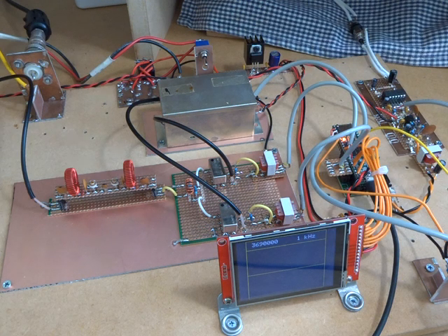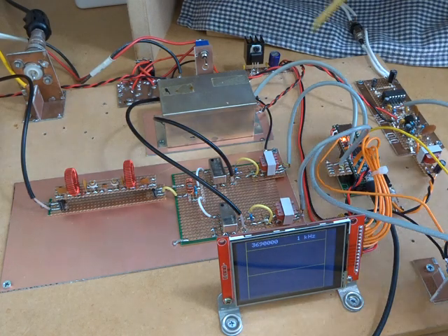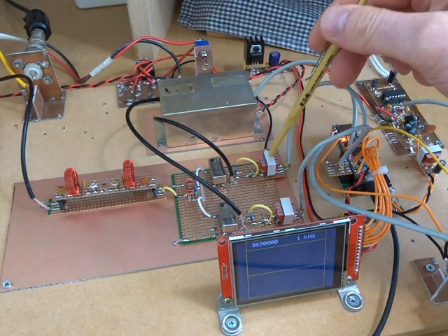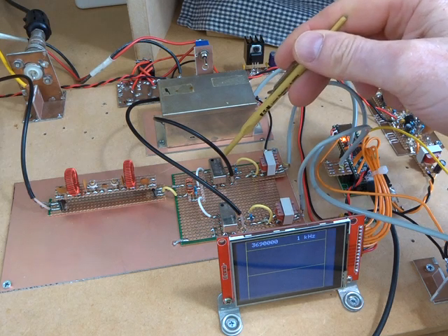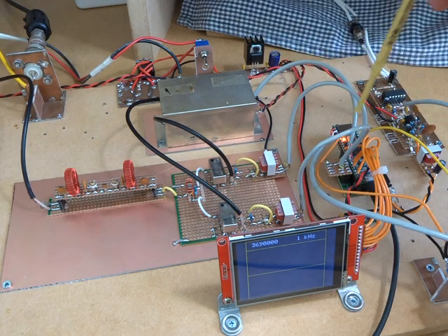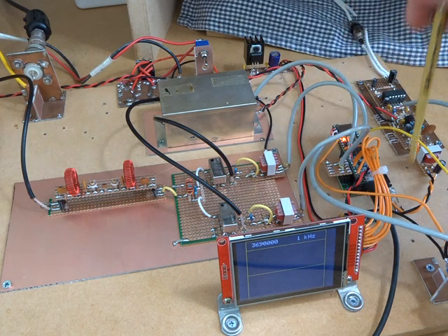So in terms of some changes since last time, what I have added is a couple of 600 to 600 ohm transformers from the output of the SBL1s and the line in to the audio control panel.